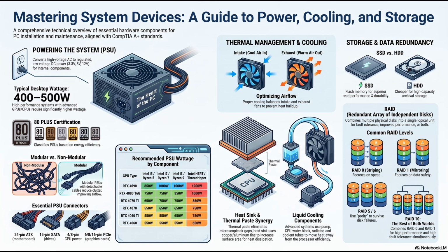Now, a massive blinking warning light for anyone listening who wants to upgrade their computer's memory. If you own a PC built 4 years ago, it likely uses DDR4. If you walk into a store today and buy the newest, fastest, incredibly expensive DDR5 memory sticks, you are in for a terrible surprise. You cannot mix and match DDR generations. They are electrically and physically incompatible. If I try to shove a DDR5 stick into a DDR4 motherboard slot, will it work? It won't even fit. Hardware designers purposefully alter the physical layout of the memory module for every generation.